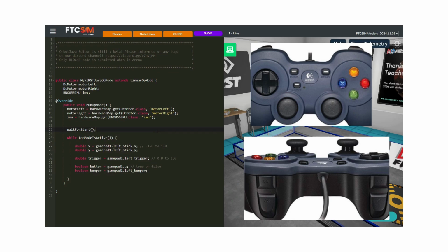You can use two gamepads to control the robot at once. You can have gamepad 1 and gamepad 2, or just one gamepad. To know which gamepad is which, you just need to remember which gamepad has been initialized and in what way. When you press Start A or Start B on a gamepad, it initializes. Pressing Start A corresponds to gamepad 1, and Start B corresponds to gamepad 2.